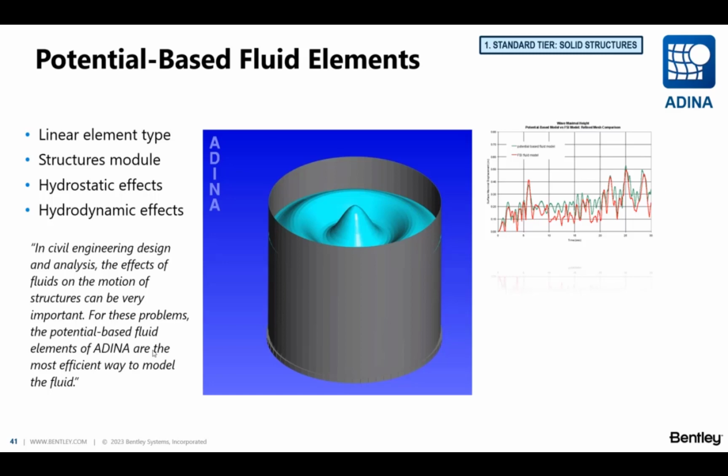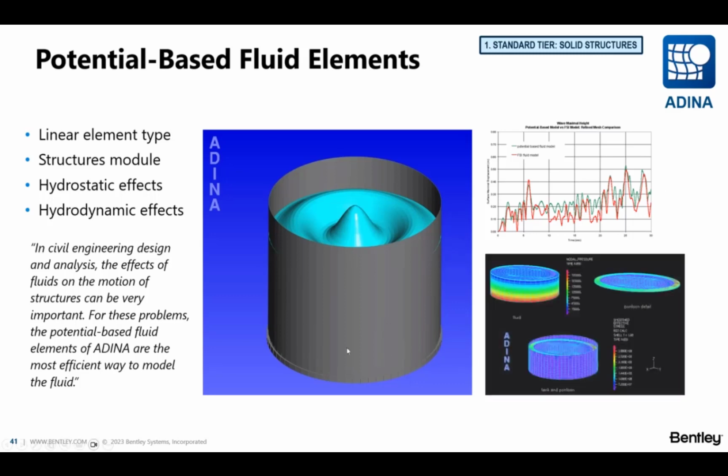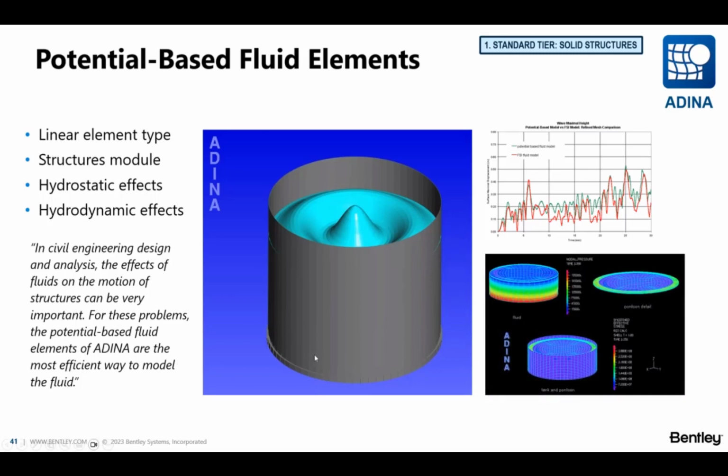It comes with the structures module, so it's not computational fluid dynamics, and we can capture hydrostatic and hydrodynamic effects in certain scenarios. We won't be able to capture very turbulent, very complex fluid phenomena, but certainly when we have a tank, of any shape, subject to an earthquake excitation, this is something we can analyze.